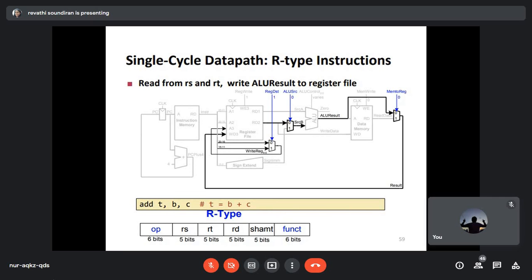Here you have to choose. Since you don't have any multiplexing operation, sorry, you don't have any signed immediate value operation, you are doing it directly from the data. Only the data is used; you don't have any signed values here. So ALU SRC being 0 is the control signal generated, and only SRC B is happening. Only the data is taken out, and no signed value comes into the picture here. In case of an immediate operation, this will be enabled to 1, so in that case only this data is being taken up.